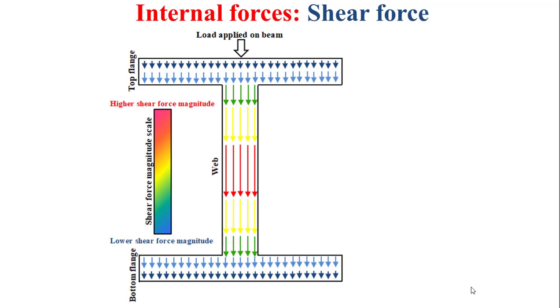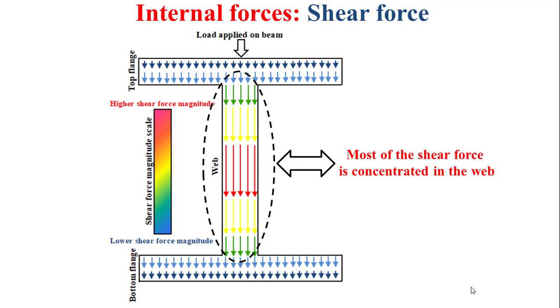Now I'll talk about the shear force, and as it is depicted by the figure that you see in this slide, higher shear force magnitudes are located in the web, while lower shear force magnitudes are located in the flanges. This means that most of the shear force is concentrated in the web. And please keep in mind this observation because it will be useful to assimilate the shear connection that I will talk about in the next educational video.